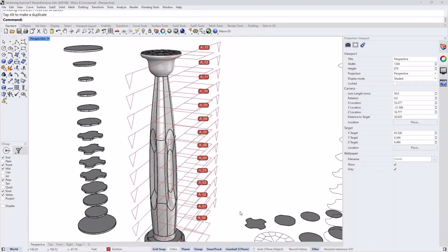What I meant is, the way you're slicing it for CNC milling or laser cutting, can we use that same strategy when we work on a model and we want to remove, let's say, a third of it or half of it? So the clipping plane becomes like a slicer. Is that only for viewing, or can you get a part of it, save it and 3D print it as a sculptural form?